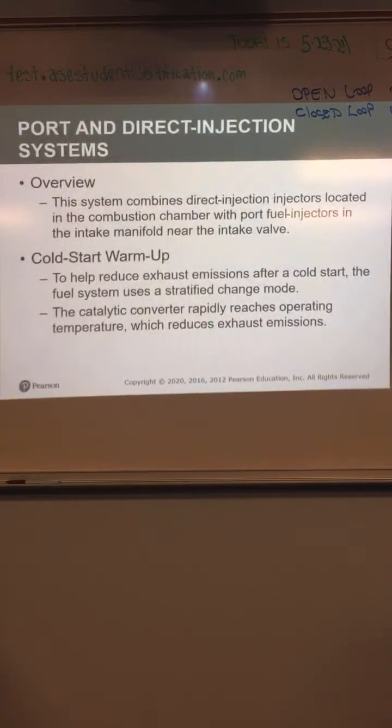Important: direct system overview. This combines direct injection, injectors located in the combustion chamber, with port fuel injectors in the intake manifold. Some manufacturers have designed a system that is both direct injection and port fuel injection both.